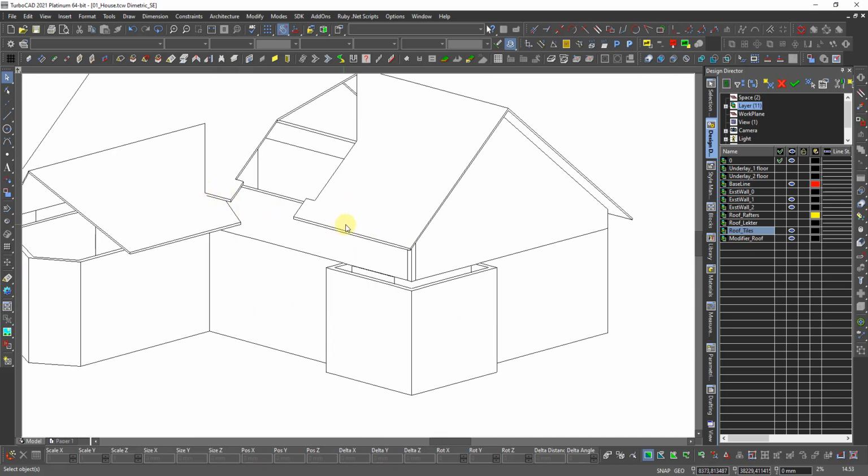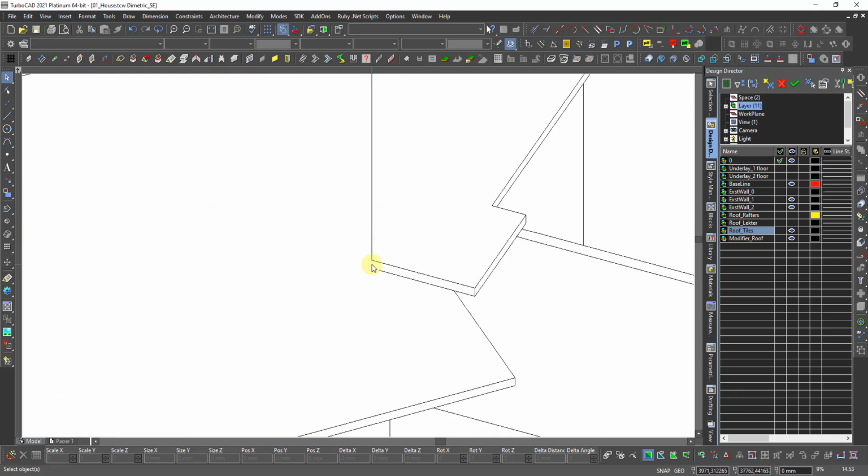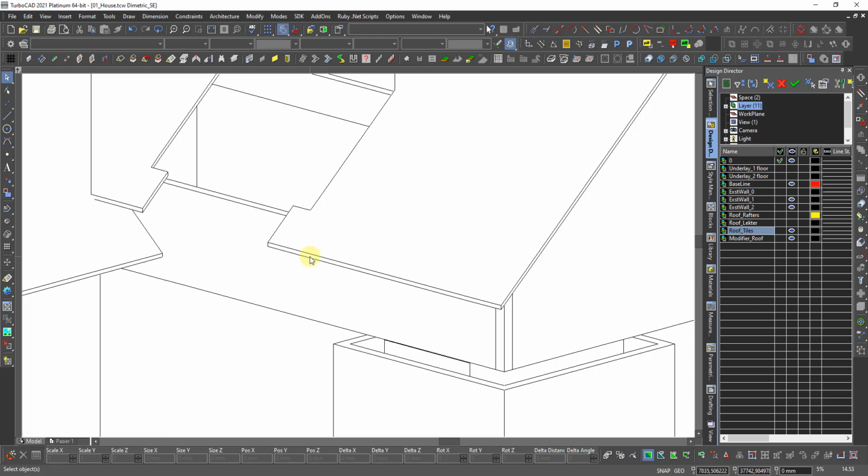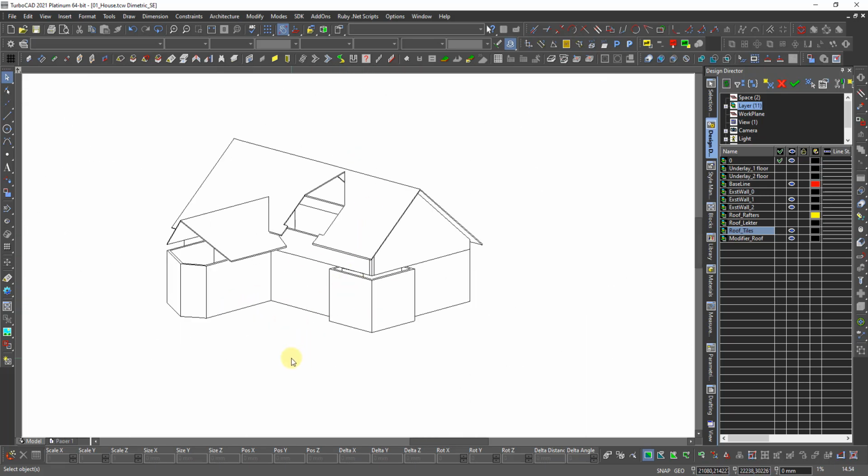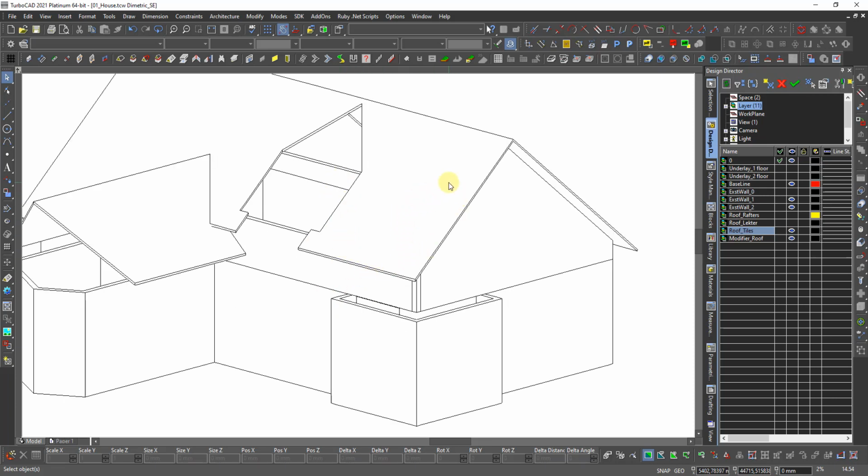But it will be like it will be later when we're putting a box over, if we cannot fix it. Then we have this and this. This looks okay. The thing when we use a modifier, we cannot change the edge. I want to have a square edge on this one, but that is not possible when I'm using a modifier. It will always be straight up. I can also try to rotate the modifier to see if it follows the object, but it didn't. It goes straight up. But if I did this to the roof slab too, I couldn't show this tool, how to make a hole in a normal roof. So that's why I keep it like this.